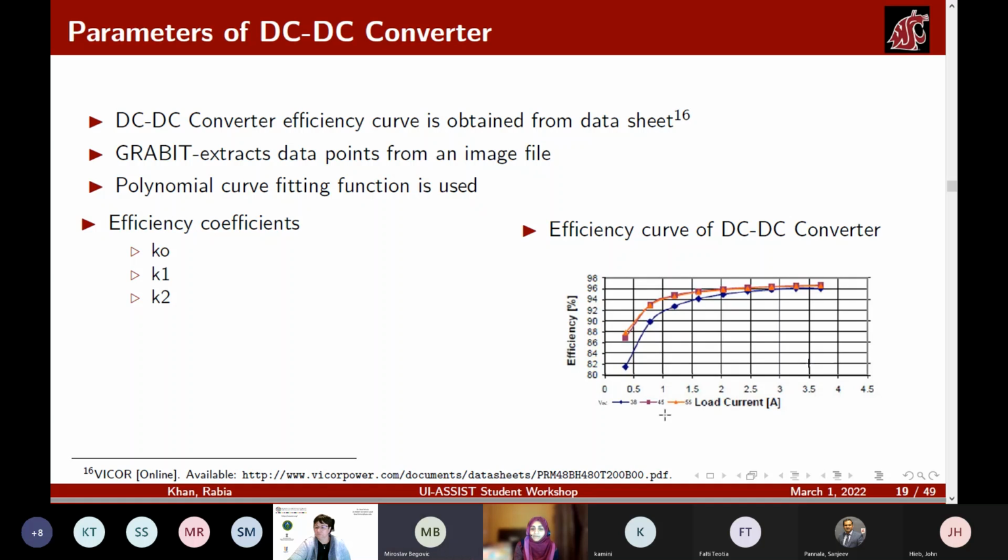The shape of these efficiency curves essentially pushes you to operate at the highest power level, closest to the nominal. There are inverters, at least the ones that we worked with when I was at Georgia Tech, which had slightly declining curves. So the maximum efficiency was not at the peak power, but at the fractional power. And that was interesting and somewhat surprising to us.